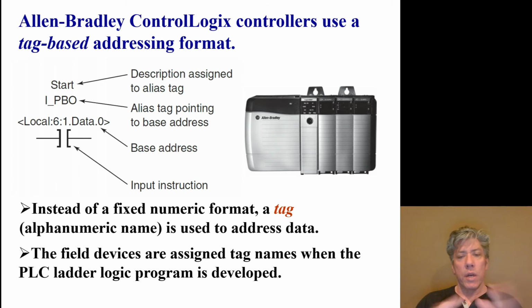So it's important to understand that no matter what flavor of PLC programming language you're talking about, these instructions are just instructions that go and reference particular memory locations that are associated with particular inputs and outputs, if it's an input type address or an output type of address.